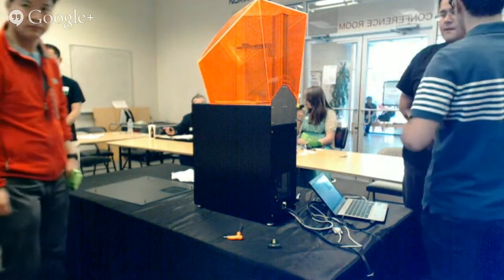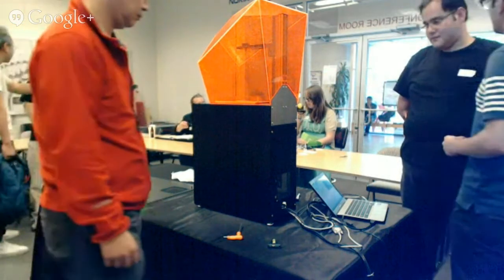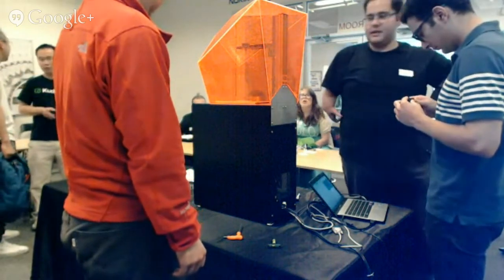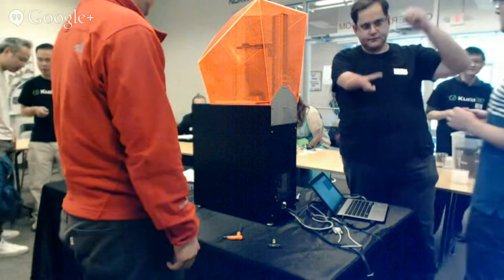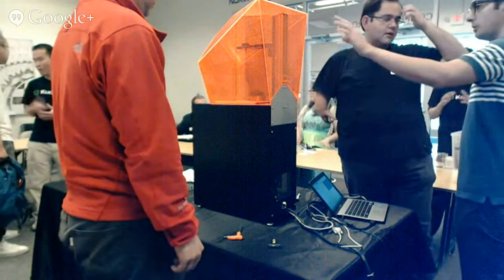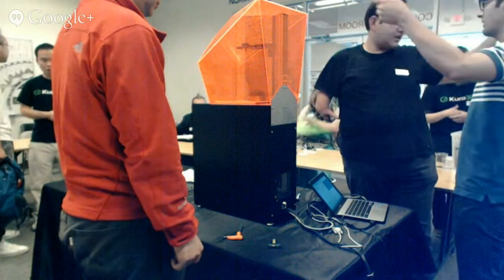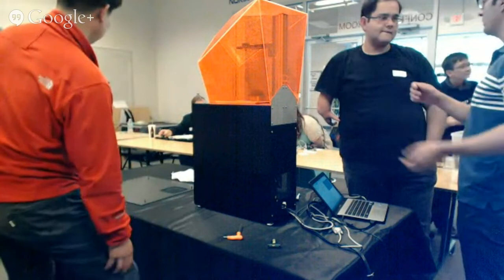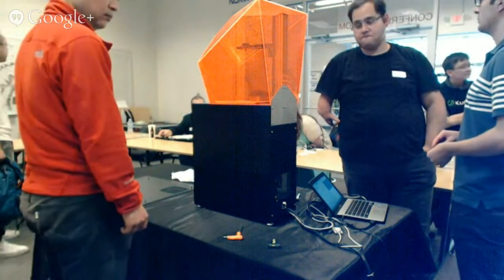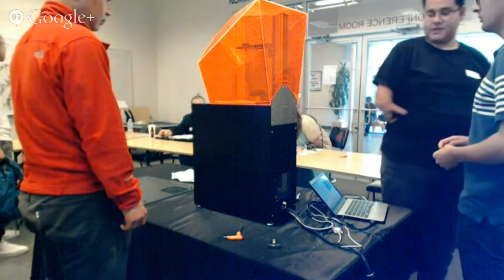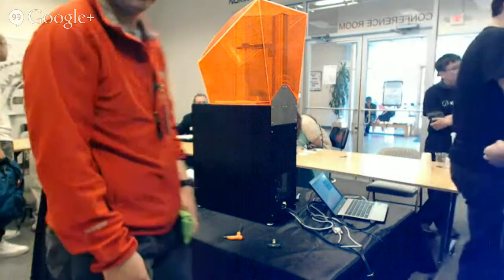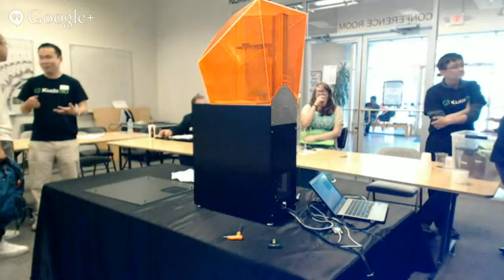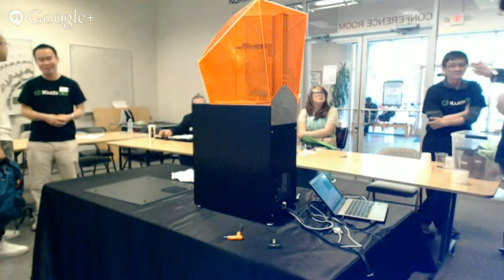It's relatively easy to see when you just look at it. So when you talk about that resolution, is that the actual resolution or the theoretical, determined by just dividing the size by the number of pixels? Or is that the real one? A micron resolution is a theoretical resolution, by dividing that size by the size of a pixel. And it represents the minimum feature size, right? Because a dead pixel you will see. You can tell that there's a dead pixel there. It does become a feature. Every missing pixel becomes a feature.